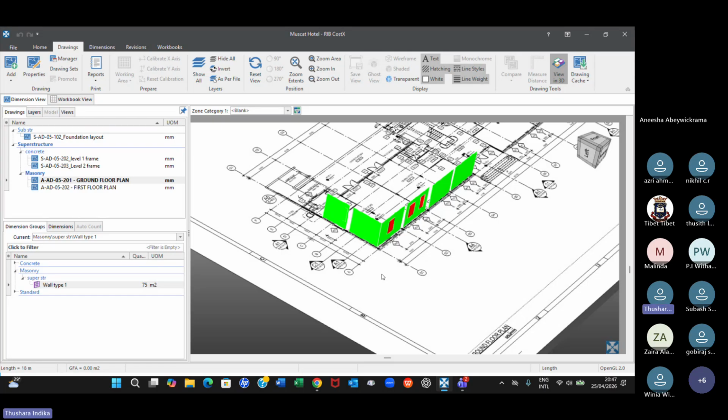Now in this case, I have measured the blockwork first. Remember the sequence. I have measured the blockwork first and then deducted the openings. For that, of course, you need negative dimension. Right? That's what we did here. Now you don't have to do that when you do the measurements of the windows first, because you already know the windows.